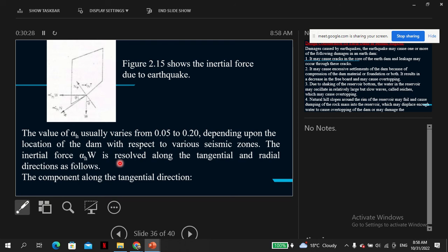There's a map for Kenya, dividing the worst scenario, which is in the Rift Valley. Fortunately, the rest of the country is fairly fine. This is not to say that they don't experience earthquakes, but you do not want to make unnecessary designs, because these things involve money, so we use some percentile, some history, some statistical data over some years, 10,000, 300, 150, and so on.